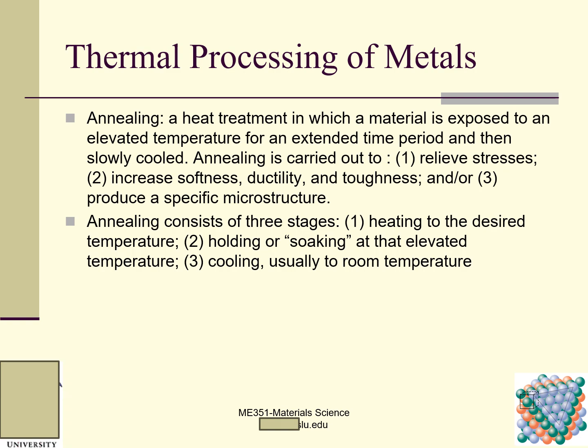Annealing consists of three stages. As I said, heating to the desired temperature, holding or soaking at that elevated temperature, and then cooling, slowly cooling, usually to room temperature, because we are usually using this kind of material at room temperature.